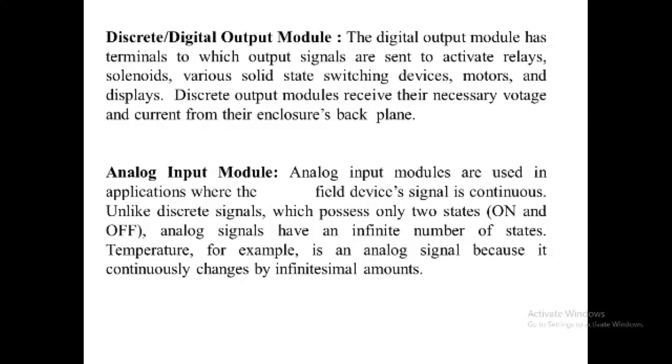The power section threshold circuit detects whether the signal has reached the threshold voltage for a specified input rating. If this input signal exceeds the threshold and remains above it for a duration equal to the filter delay, the signal is recognized as a valid input. After that, the isolation interface detects a valid signal.